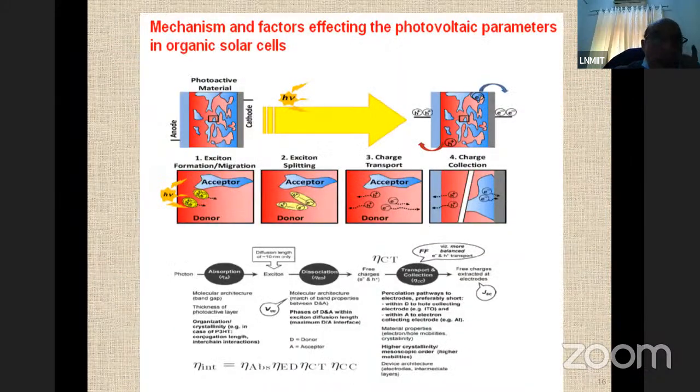Now, what is the concept here? I will now talk about the bulk heterojunction. The bulk heterojunction active layer is sandwiched between two electrodes, that is your anode here and cathode here. Once the light is incident, what happens? The first process is that excitons are generated. The number of excitons generated in the active layer depends upon the absorption profile of the active layer, the combination of P and N-type material. Once the excitons are generated, they will dissociate into free charge carriers.